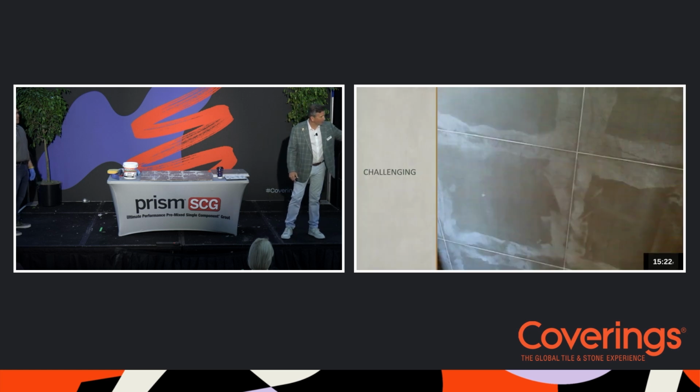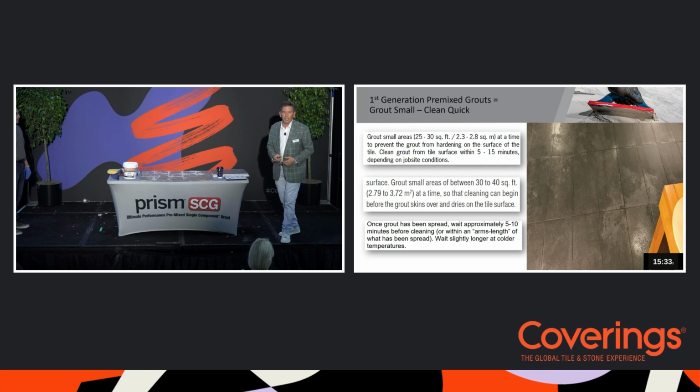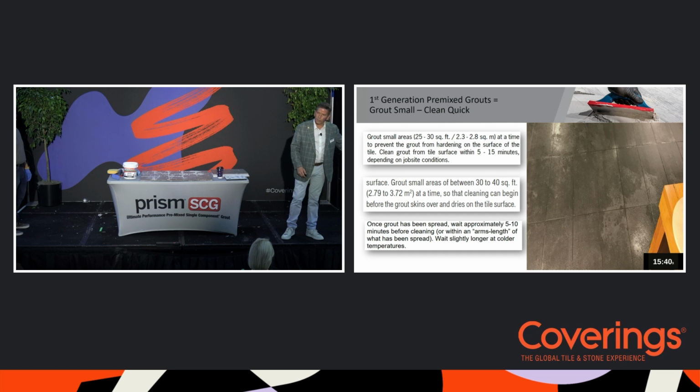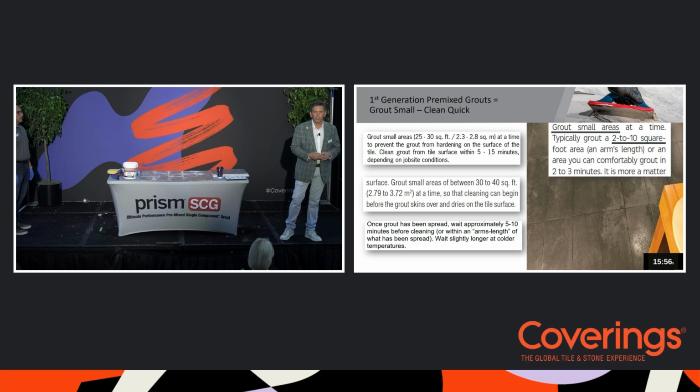Now this slide shows you some typical results of using that first generation premix grout. Very challenging because it required the contractors to grout and clean right away. Very short working time. Even more difficult than using epoxy in most cases. Now these are excerpts from current technical data sheet instructions for the first gen category. And if you look here, there's another one that says 2 to 10 square feet. Can you imagine telling the contractor, you can only grout 2 to 10 square feet, then you have to clean it up. So that changes the way they grout.